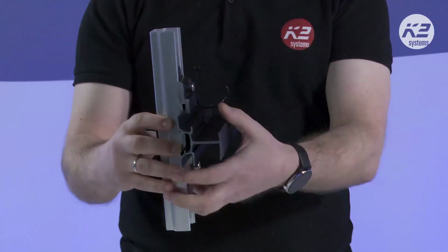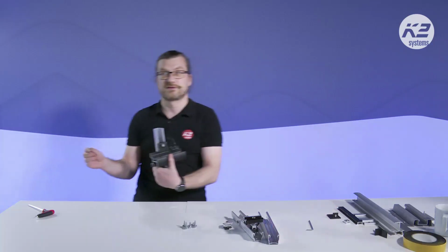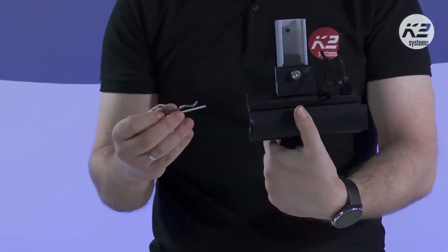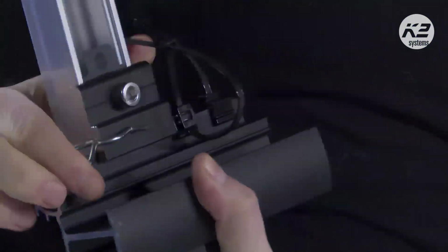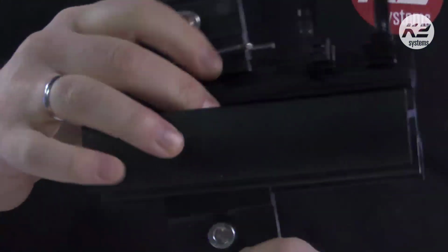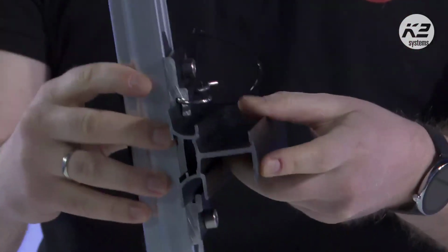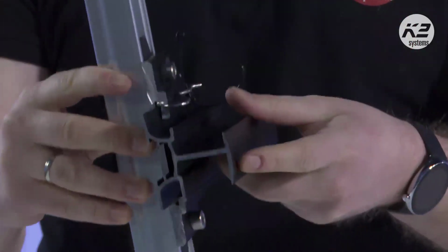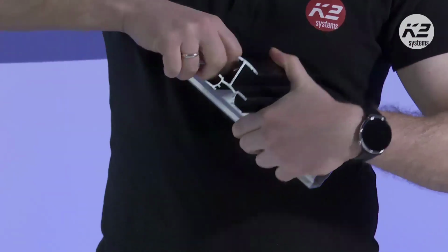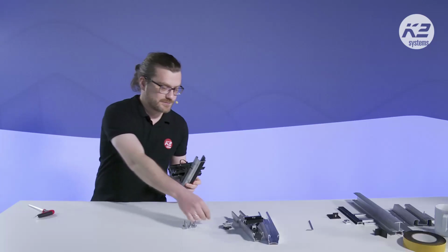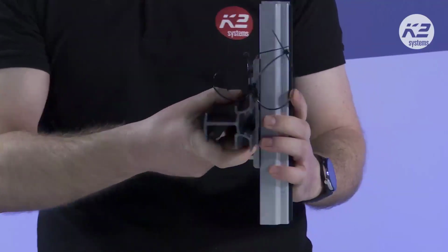In every second cross connector, we install such a simple spring plug. This one. Simple to install. You just move it inside the cross connector. So as soon as the spring plug is installed, you see that there's no space for the rail to go out. This spring plug prevents the insertion rail from going up and down, but the insertion rail can move to the left and to the right.